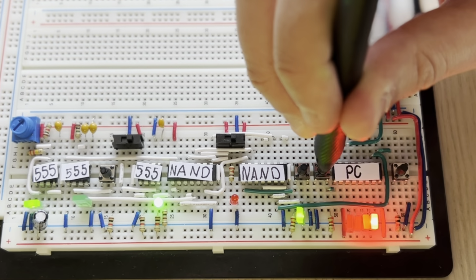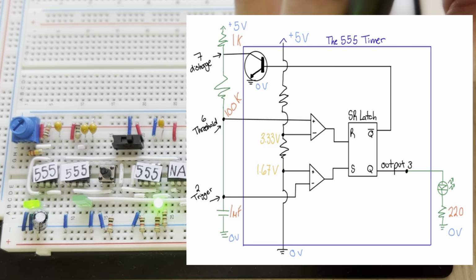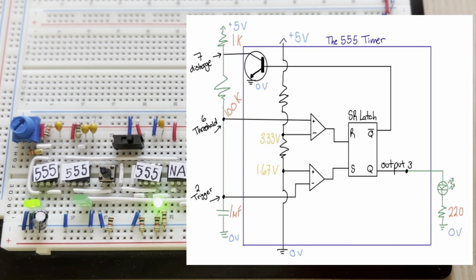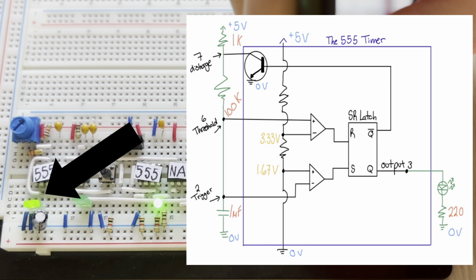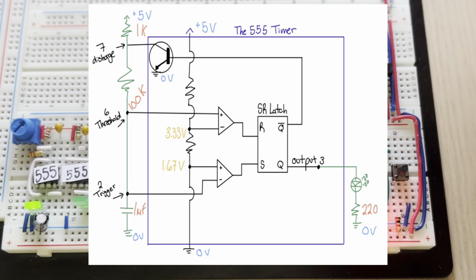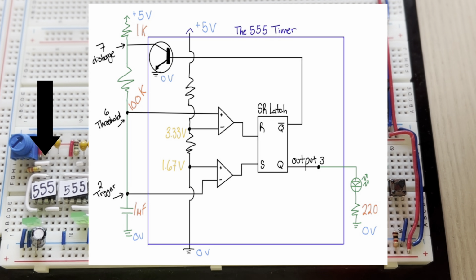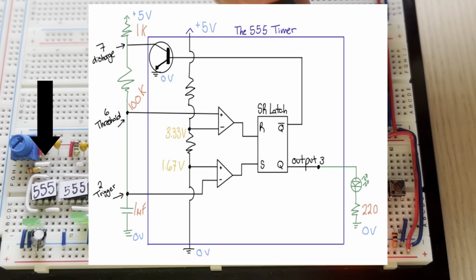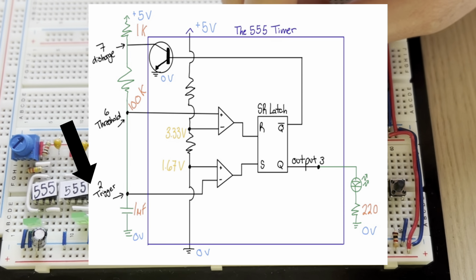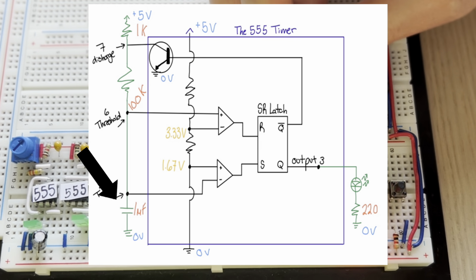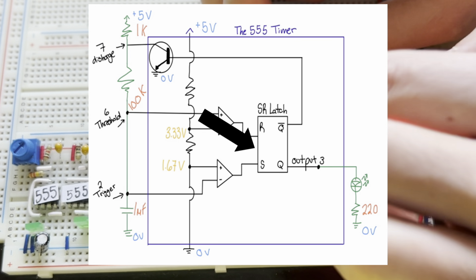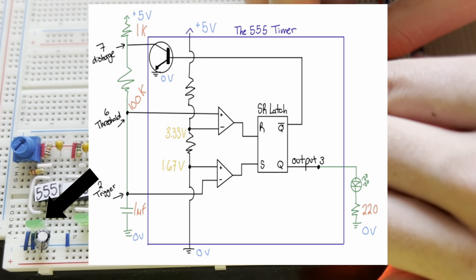In the context of the 555 timers, astable mode refers to one of the operational configurations where it functions as an oscillator. In this mode, the timer continuously switches between its high and low states, generating a square wave output. This is apparent as looking at the internal components of the 555 IC. The rise and fall of the capacitor as it gains and loses voltage causes the SR latch inside to switch between releasing a high and low output at a stable rate.